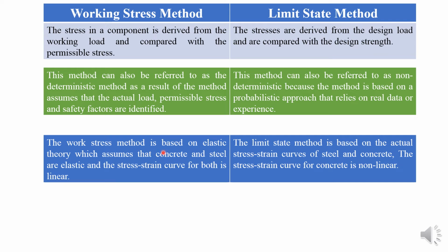The working stress method is based on elastic theory, which assumes that concrete and steel are elastic and the stress strain curve for both is linear. The limit state method is based on actual stress strain curve for steel and concrete. The stress strain curve for concrete is non-linear.